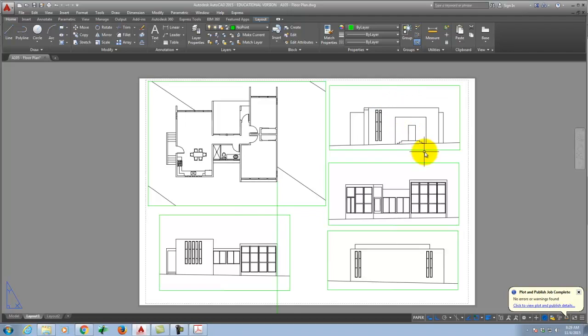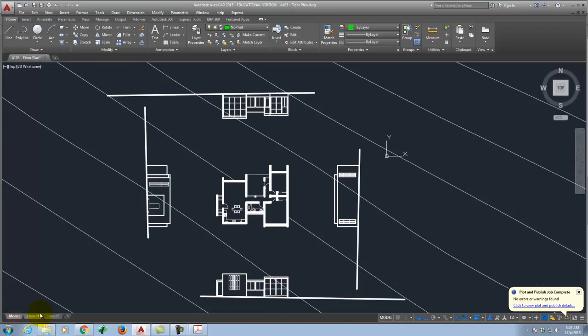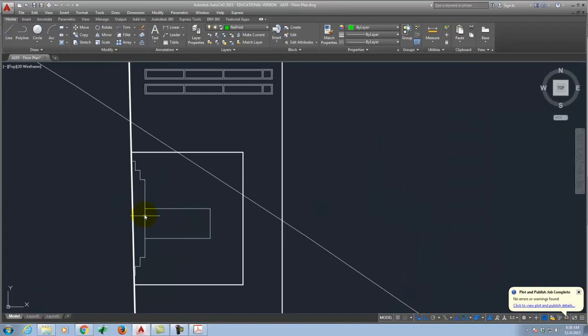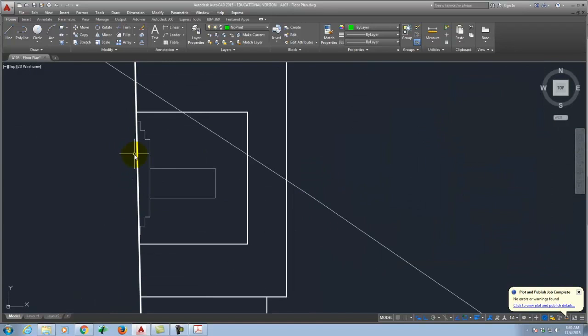So you guys, some of you have asked me previously how to show the hidden lines. We've worked through it, or maybe we haven't yet, but you couldn't see them in Model Space. When you move to Paper Space is when you'll see the hidden lines. This little set of stairs is inside of a wall, but I drew this specifically so that we could make this a hidden line, so you could see what a hidden line would look like.